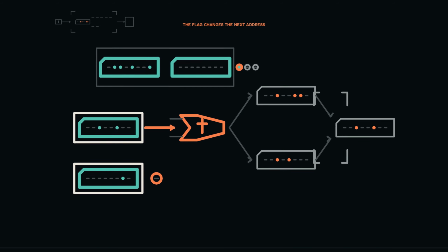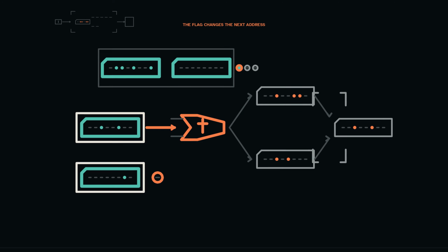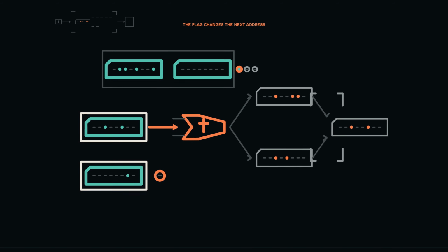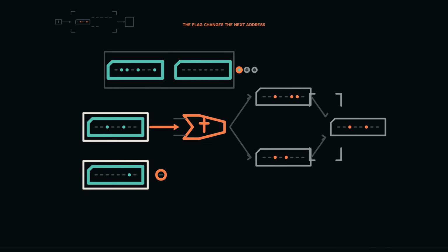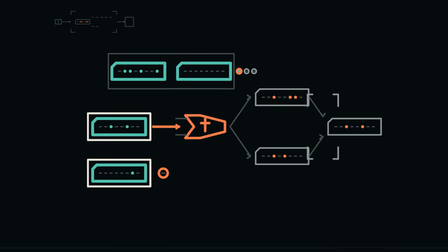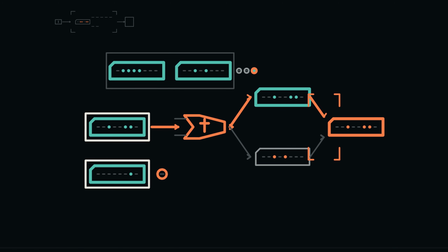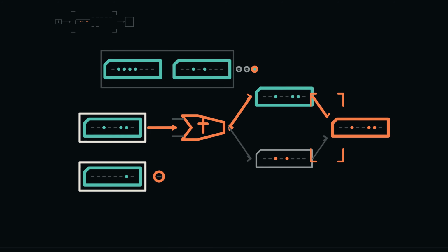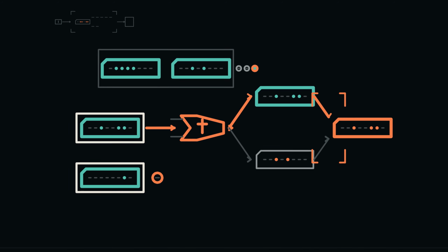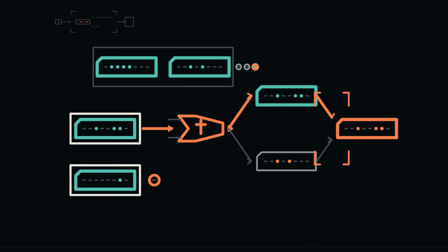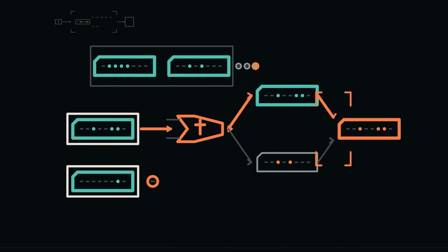Comparison has not moved PC to either destination. It has created one stored fact the next instruction is allowed to inspect. That temporal separation matters. First compute and capture the flag, then fetch a branch whose contract uses it. A road junction supplies one limited relation. An arriving route can continue normally or take a named turn according to one condition. Map the normal route to the PC already advanced by fetch, the turn to the encoded target, and the condition to a flag, then stop the comparison.